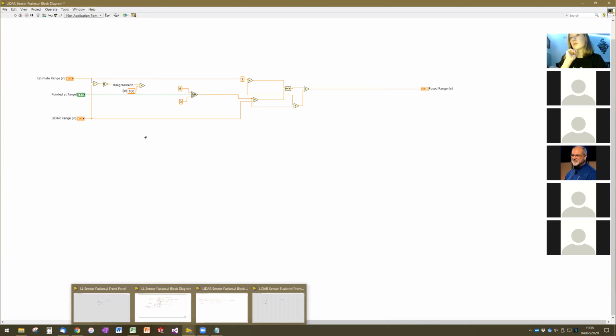Well, if the Limelight or the odometry gets off. But aren't we already checking if we're putting out the target for LIDAR, so it wouldn't be the LIDAR? So you're right that the odometry could normally get off. I will say that the thing that usually makes the odometry all of a sudden be very, very wrong is if it gets a bad Limelight signal. And we are actually already doing this exact kind of check for the estimate position. So there's another one of these disagreement checks embedded in this one.